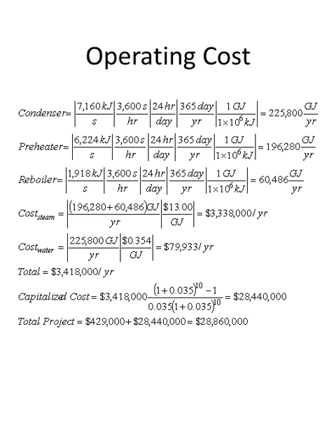Add that to the slightly more than $400,000 for the capital equipment. Our total project is $28,860,000. Notice that the operating cost is the biggest portion of this. And so we ought to design our tower not to minimize its size, but actually to minimize its utility usage. And this can be done by looking at different reflux ratio and different feed conditions.